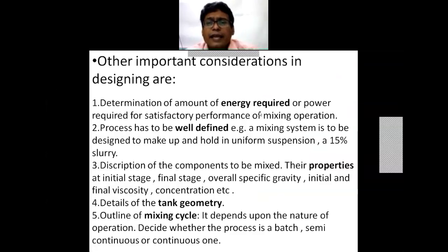Then the energy requirement is one of the most important aspects to be studied in our agitation system. Power consumption: is my energy getting wasted in turbulence and shearing, or is it only utilized for the purpose of mixing?